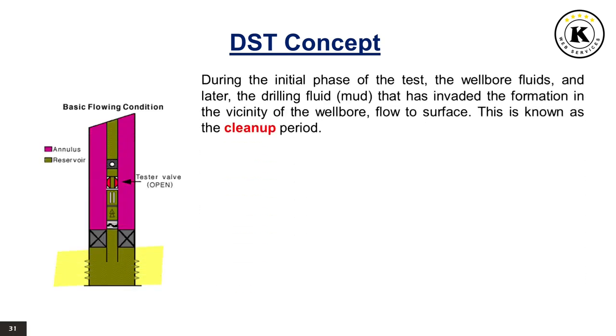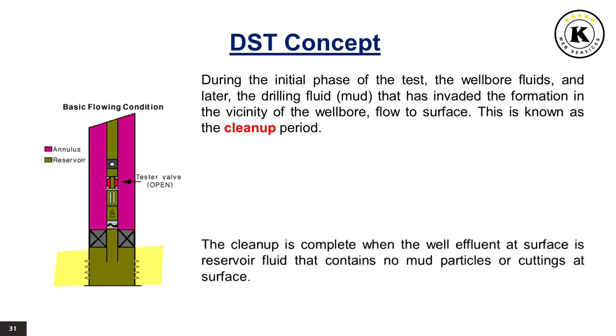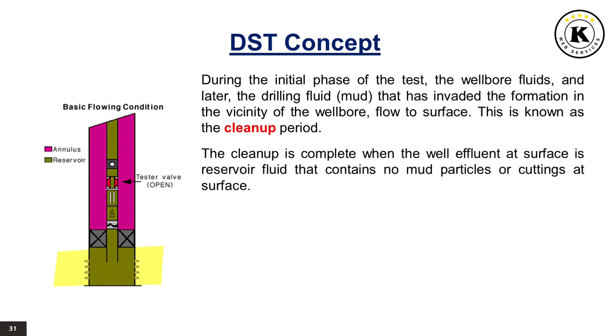During the initial phase of the test, the wellbore fluids, and later, the drilling fluid, mud, that has invaded the formation in the vicinity of the wellbore, flow to surface. This is known as the cleanup period. The cleanup is complete when the well effluent at surface is reservoir fluid that contains no mud particles or cuttings at surface.